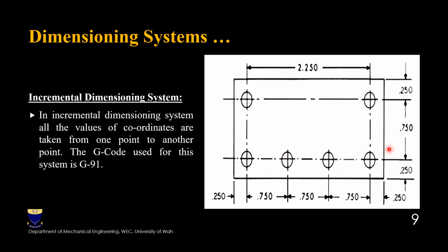So the other increments with respect to these holes are right, which are 0.75, 0.75, and 0.75 in y and minus 2.25 in x direction. But all the drill holes after this drill hole will not be at their proper position. So that is why it is generally recommended to use absolute dimensioning system to avoid mistakes in program block.